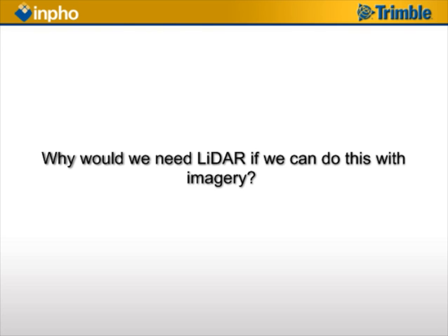So they're flying with their LiDAR once or twice, creating their height database, and then whenever they are flying for creating new orthophotos, they're just using the same photo flight to update in smaller parts their existing height model.